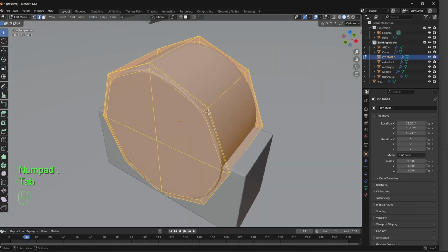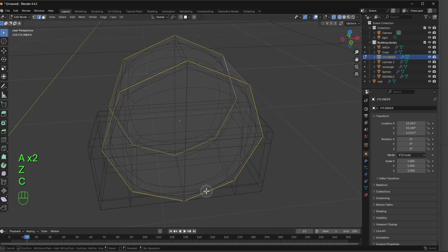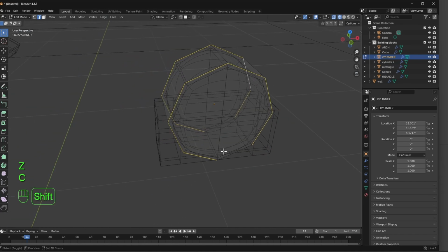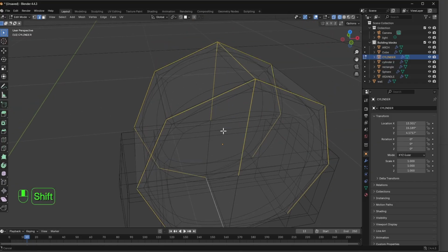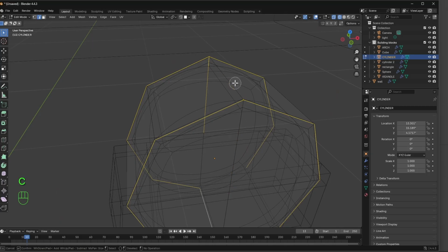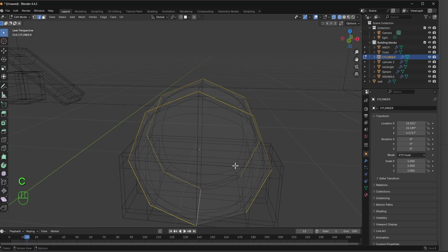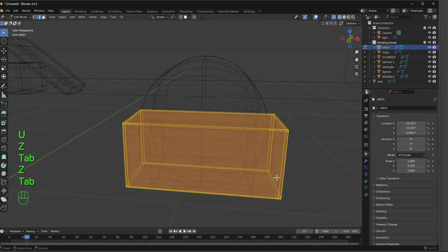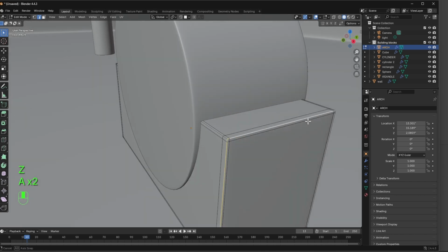Now we're going to UV unwrap, which essentially is taking a paper cube and flattening it so that it's a 2D image so that we can put textures on it. Depending on the quality of your textures, mark seam. You want to make the edge loops not so noticeable, but that depends on the type of object that you're making as well.